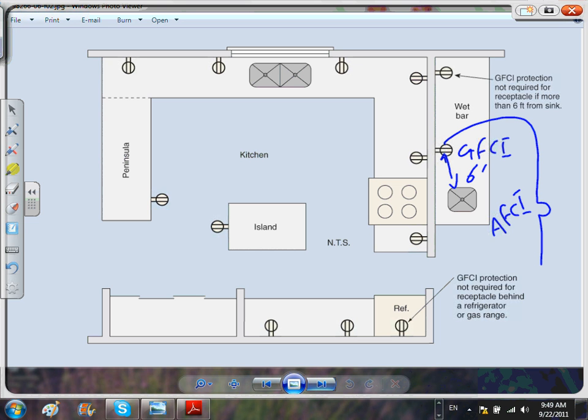I was talking to Tao during the break, and I told him that when you guys go commercial industrial, we have a 4,000 amp switch, 4,000 amp circuit breakers. Imagine 2 feet by 2 feet by 2 feet. That's how big that boy is. And that circuit breaker, you can dial it from your laptop, pull all the information from it: the current, the voltage, the frequency, the harmonics. You can ask that circuit breaker to open or close.